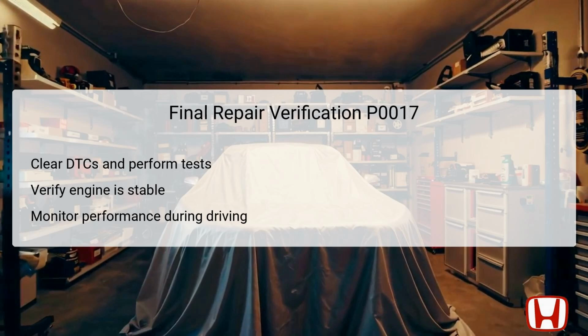Conduct a short drive while monitoring for any potential performance issues and be on the lookout for the check engine light illuminating again. This step acts as a quality assurance check to verify that all components are performing correctly and that the issue associated with the DTC has been resolved. If all tests pass, this signifies the repair process is complete.